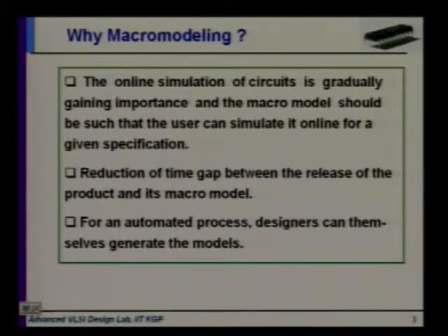So why is a macro model done? First of all, suppose you have designed an op-amp of good specification. Now I want to use your op-amp and fit it in my system. If I want to purchase it from you, you can't make the actual transistor level design available to me. So you can give me the macro model of the op-amp circuit, which is of the same specification. I will fit the model in my environment, simulate it, and test whether all my criteria are being satisfied or not. That is the intention to use the macro model.